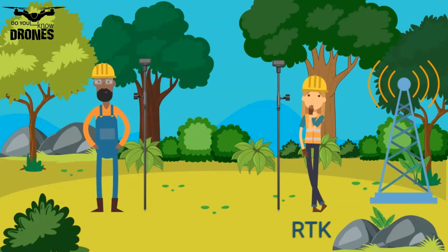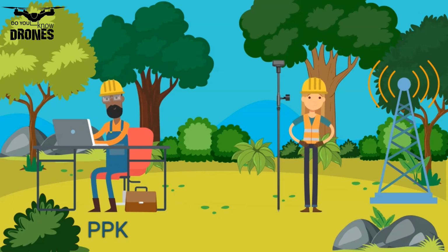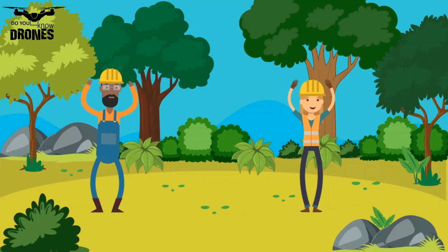RTK requires a base station with a known location to send correction signals to the rover in real time, allowing for high accuracy measurements. PPK requires the GPS data collected on site to be post-processed with the base station data to achieve high accuracy. Both techniques have their advantages and disadvantages. It's important to choose the right one for the job.